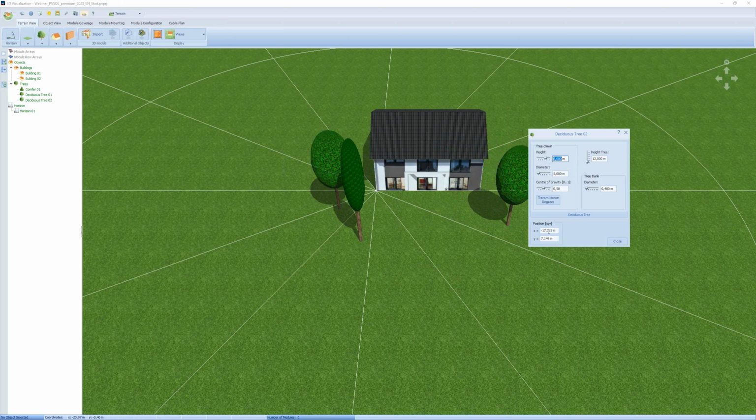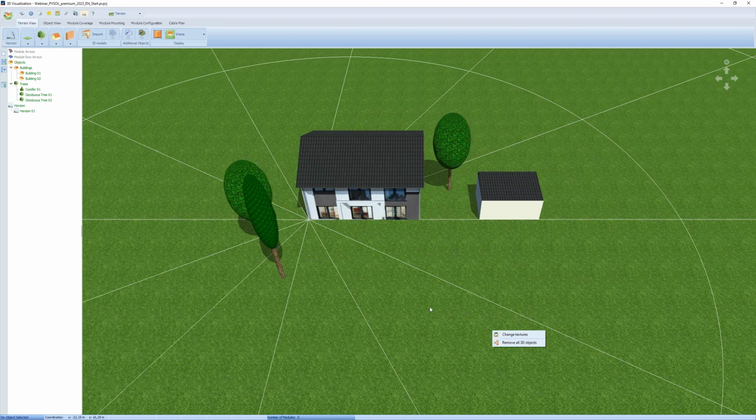Okay, now I have to enter the position, and it's minus 19 and minus 6, I think. Yes, minus 6. Okay, that's it for the terrain. Now we have defined two buildings. We have changed the textures. We have added a second building for a rack system, and we have also 3 shading objects. And now we would like to focus on top of the building with the gabled roof to define shading objects as well as barred areas directly on top of the roof.